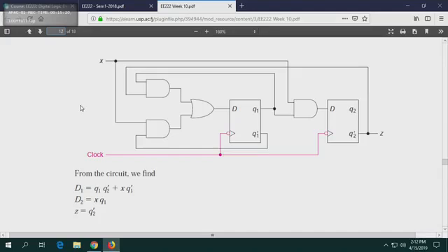Then again somebody presses the clock button. When somebody presses the clock button, those flip-flops will change state. That's the proper term, not reset. So on the sixth clock pulse, it's supposed to have 11. 11 is 1, 0, 1, 1. So the most significant flip-flop will have 1, the second will have 0, the third will have 1, and the least significant flip-flop will have 1. Then somebody presses the clock button again. It's supposed to loop back to 0, 0, 0, 1, as I said that was the design of the problem. That's what we are trying to do.